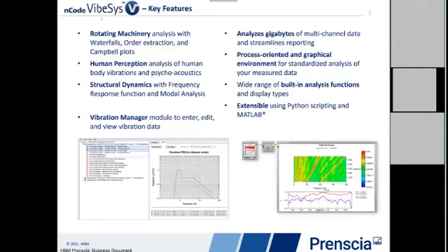But if I just end up talking VibeSys in general, we also have a vibration manager, which is very useful because it contains all sorts of typical vibration profiles that you can find in various standards, military or civil standards, and you can compare them with your measurements. You can add your own profiles, your own in-house qualification profiles or reference profiles. So that's a database of vibration spectra.